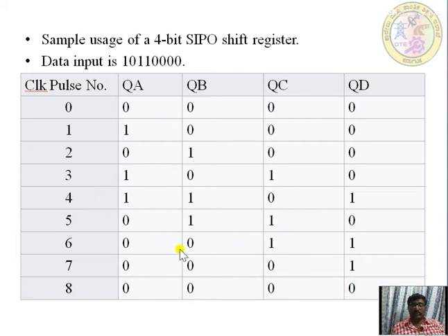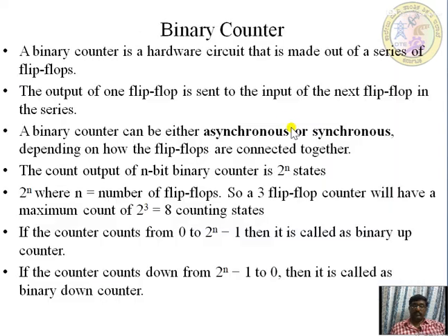At the last, all the 8 bits will be 0. See here, the output we will have as soon as we give the inputs 1 0 1 1 is all 4 zeros, and the output we are looking at is 0 0 0 0. So this one is just the serial-in parallel-out shift register. This sequence can be anything, whatever the sequence is, it just shifts with the next clock pulse, whatever the value is, from the previous flip-flop to the next flip-flop.